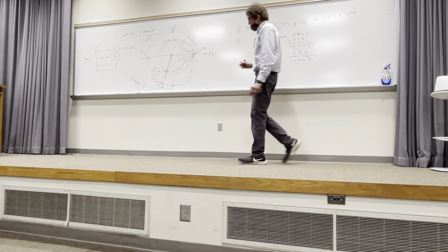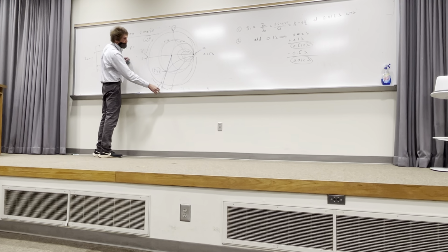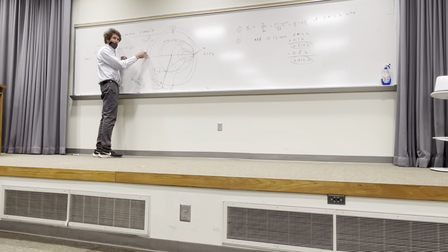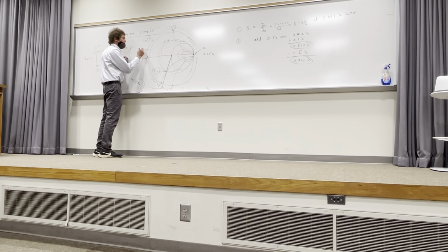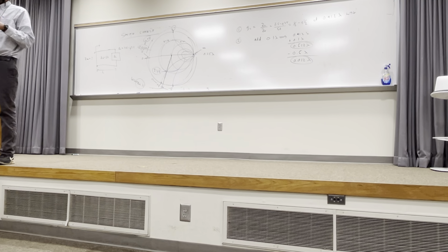Really what I'm doing is kind of obvious. I'm here, I've got to move to a point 0.512 that doesn't exist. So what I do is subtract the half wavelength and I land, if you can estimate it, on the point with wavelengths towards generator that is 0.012 lambda. You might have to interpolate. A lot of times you are between two values. The value you're looking for might not be stated explicitly, but there might be 0.1 and 0.2, so you can extrapolate to 0.12. Can y'all follow me on that?